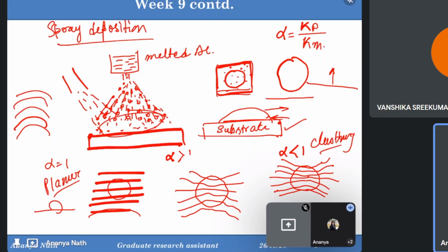But there are also a lot of problems related to non-heat-treatable alloys, because after welding or additive manufacturing, you often go for heat treatment to reduce the residual stress. Due to the repetitive heating-cooling cycle and the high power energy density, the residual stress is very high in welding or additive manufacturing. Residual stress leads to hot cracking, cold cracking, or fracture toughness problems inside the material. To get rid of that, we go for heat treatment. So the 3000, 4000, and 5000 series will not get this benefit of reducing residual stress with heat treatment. That is one problem related to non-heat-treatable alloys.